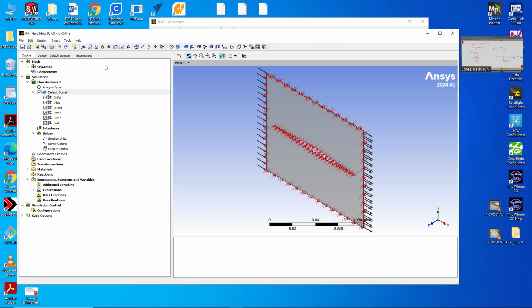You can skip a transition, probably, because the transition is like the first cell. Maybe it's not that high, because we're flying in the upper atmosphere. Anyway, we skip it just because of the calculation cost, because those tiny cells would make the time step ridiculously tiny. They technically would alter the solution slightly.